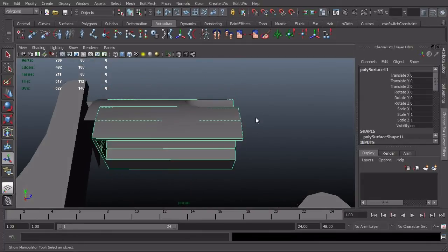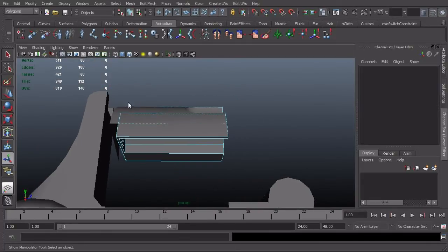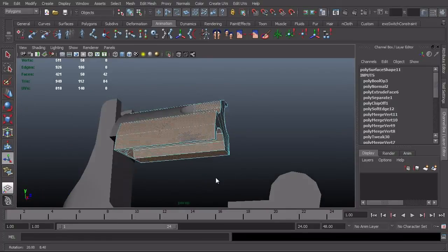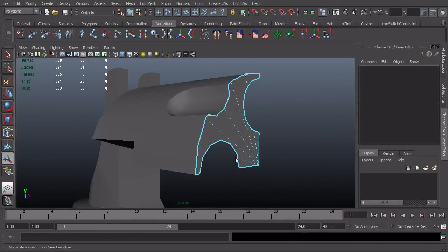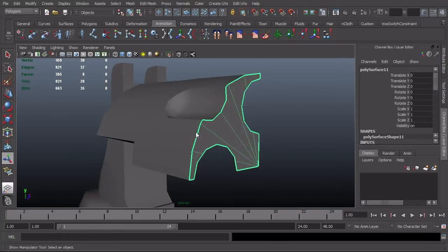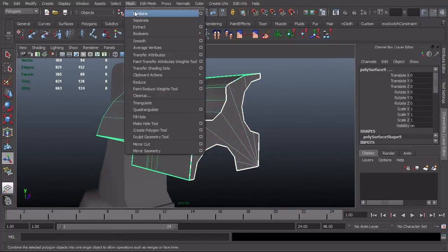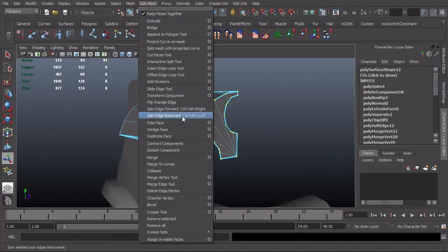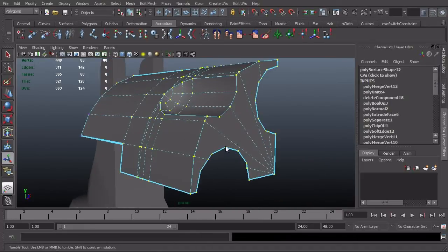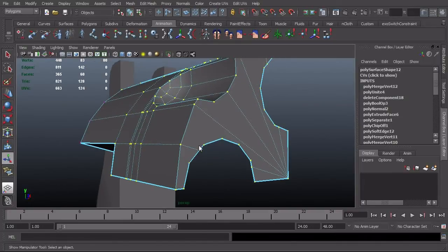We don't really care about anything on this thing except for the front face. We just had to add all this volume because Maya wanted us to, basically. So I'll go ahead and combine these two objects back together, just put it back the way it was. Do a merge. Again, you want to make sure that you have a very low tolerance on your merge. I use about 1/1000th, something like that.